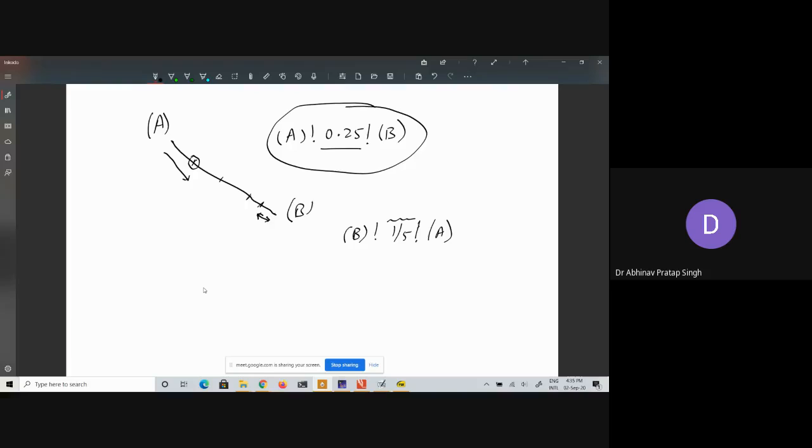Now it will be very difficult for you to calculate this fraction, but you don't have to calculate that fraction because the syntax is very similar, and I think it is very intuitive as well. You simply write A, again you put an exclamation mark, and instead of writing simply 1, I will write 1 centimeter, then the same thing again. That's it. So if you give some number along with its unit, then it will move by that particular distance.